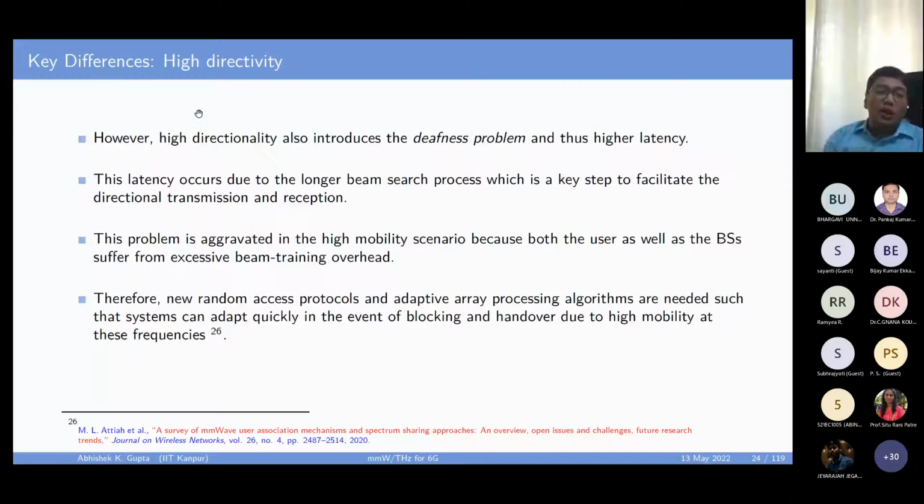In millimeter wave, even the search cannot occur without using antennas, and when you use antennas, you can only look in a particular direction. So to scan all directions, you use more time slots so that you can beamform in each direction and search over that. That increases your overall search process.